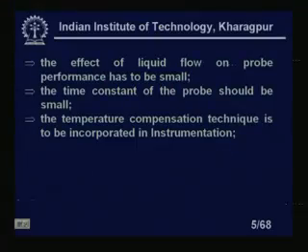Usually in bioreactors, we are not much concerned with this. You will find that in most bioreaction cases the time constant is typically large. Suppose there is a reaction which is going on for 72 hours, or 48 hours. Even if you sample each sensor's output every 6 or 10 minutes, that is quite high, because any reaction takes a long time. It does not change so rapidly that you have to sample every minute.